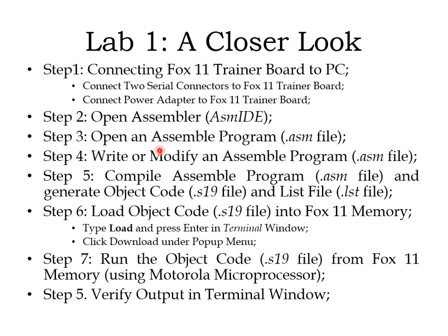Now, there are 2 things. Number 1, how do you start? We have the board with us. You have to connect the board with the PC, which means a physical connection. How do you connect? We need to connect these 2 lines, these serial connectors. We'll show you the image here. And also we'll power it up. There is an adapter; using the adapter, we'll power it up. So there are 2 different things to activate this board physically and connect it with the PC.